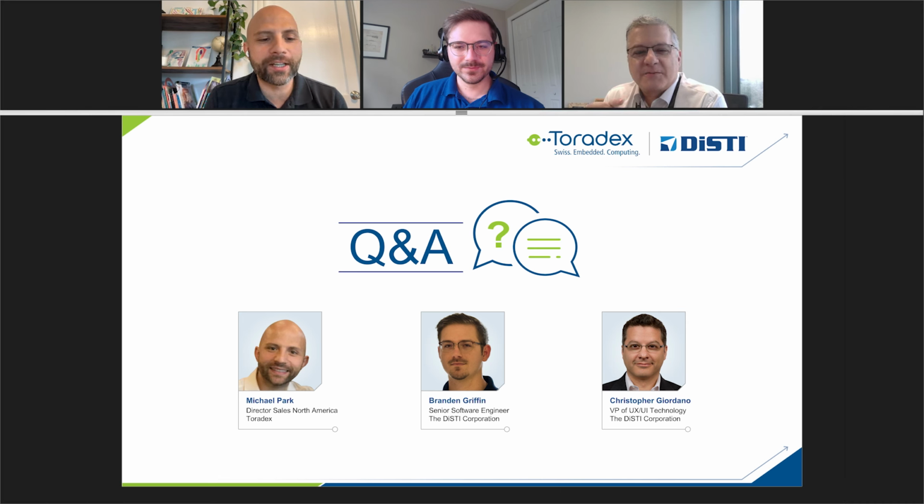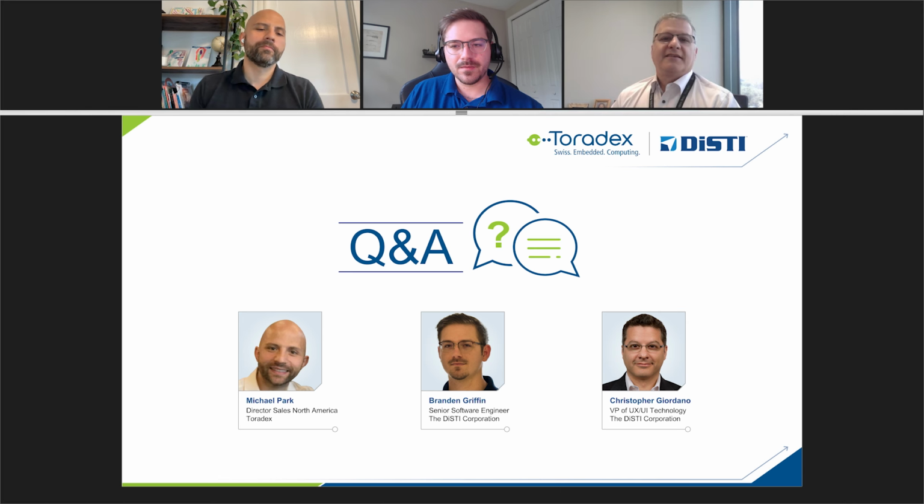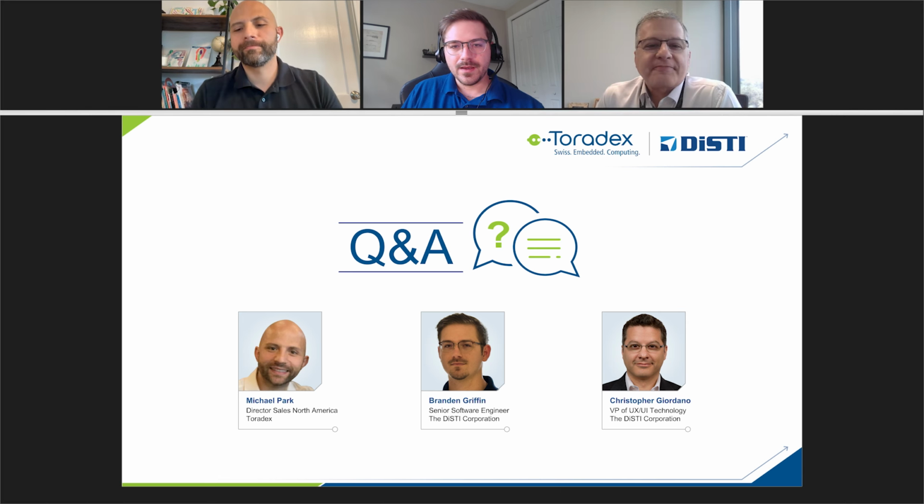So here we go. How does GL Studio support reading and processing inputs from the other sensors connected to the HMI? Yeah, so it really depends exactly what your system looks like. GL Studio has a C++ public interface, which we talked about a little bit with our properties, and those are exposed so that you can send in data from other sources.